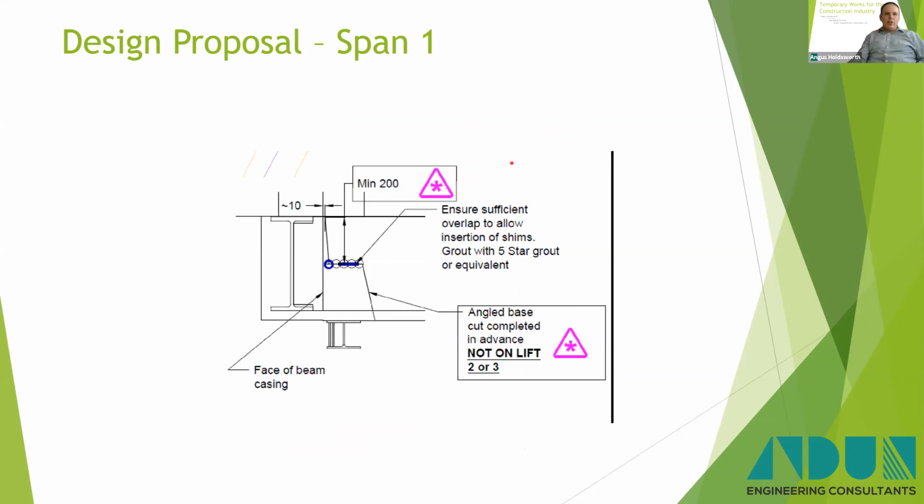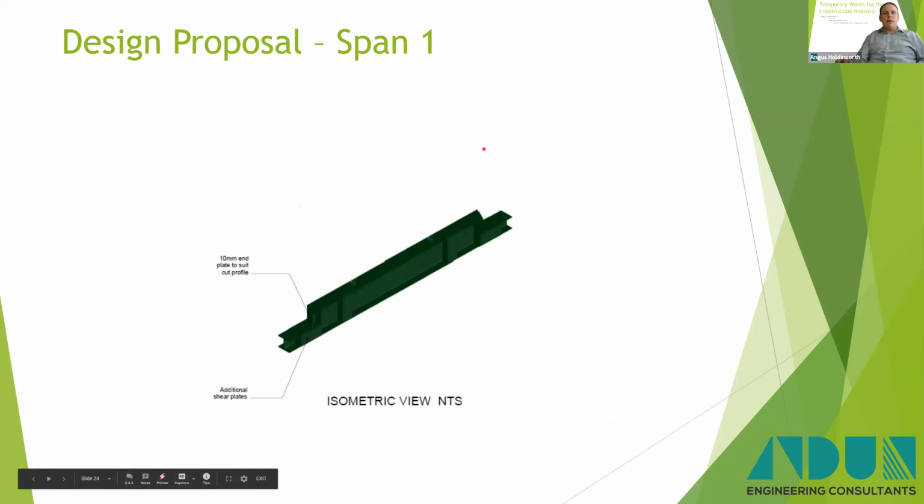So the detail of the packing. Where we did a sit cut in the beam, we had to have the potential for it to sit there for a week with the railway open. If it went wrong in the first possession, we put a proper bearing back in. So we cored out 4-5 core holes, and then we formed a little bearing within there by grouting some steel plates in, and then we finished the saw cuts so it could actually sit there properly on a bearing, and we knew where the load was being applied, which is directly above the steel beam there that supports the span in place. That's one of the steel beams that was lifted up underneath to support the bridge.